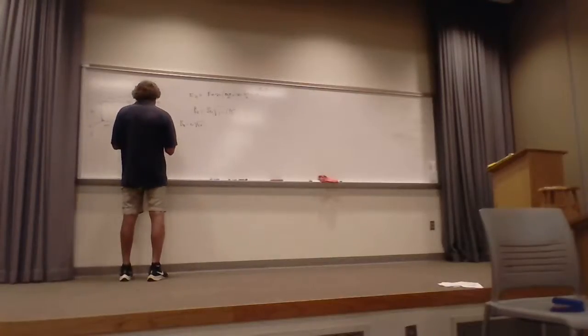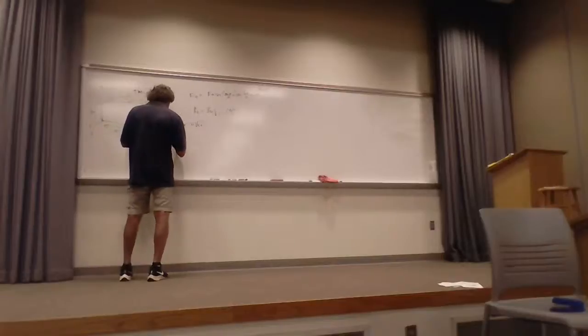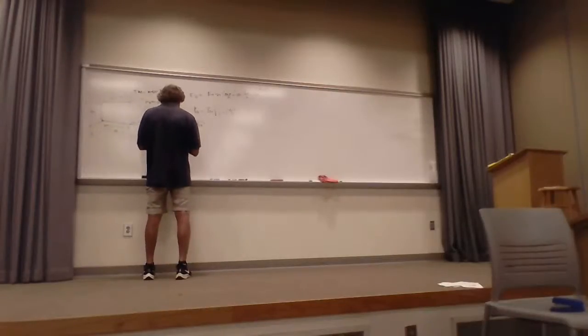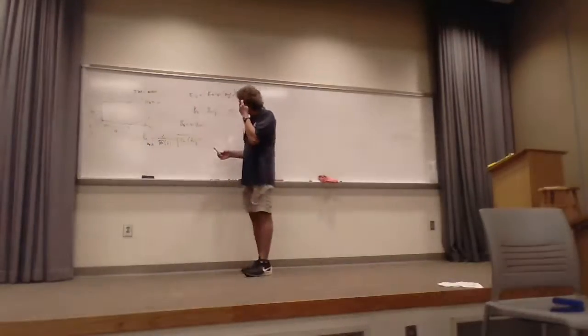The cutoff frequency is really going to be the speed of light, C, divided by the square root of epsilon relative, divided by 2. And then it's going to be times the square root of 1 minus (FC over F) squared. Now, I'll just tell you where this came from.